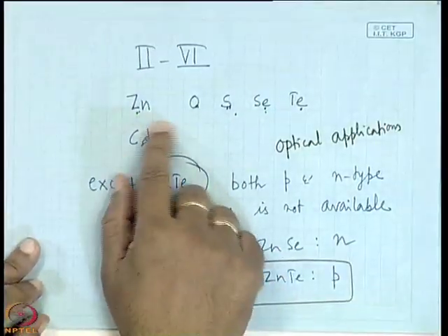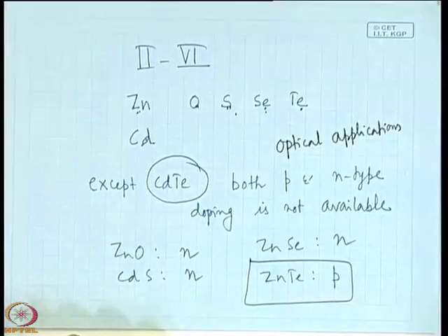Another important material which we should discuss is zinc oxide. Zinc oxide is one very important material. Its exciton binding energy is 60 milli electron volt. What is the room temperature thermal energy generally? 26 milli electron volt. So, 60 means almost 2.2 to 2.3 times. That means even at room temperature, the exciton binding energy is higher than the thermal energy.